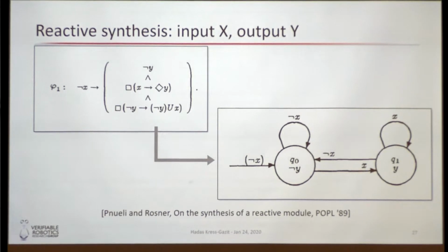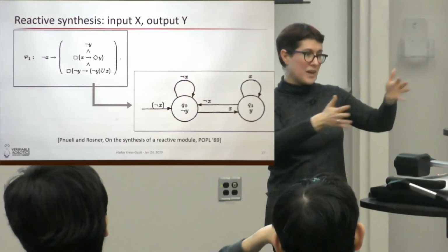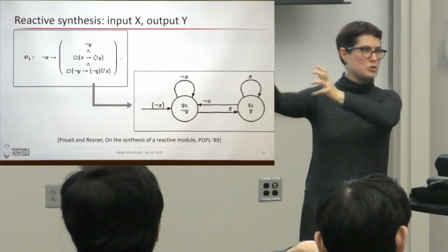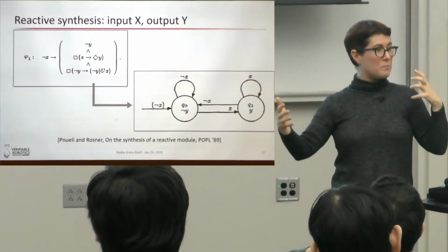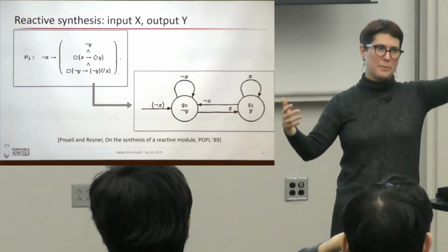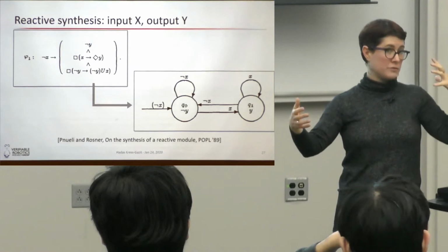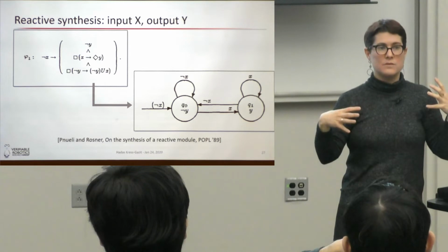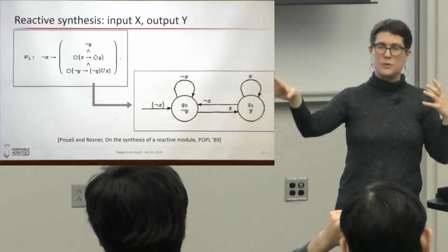The idea there is you have propositions that are inputs and propositions that are outputs. In robotics speak, we have sensors, or perception information, and we have actions, or actuation, or control. The information I'm getting, I'm not controlling. That's the environment, they're doing their thing. I'm getting information from that. What I'm controlling is what my actions are, the robot's actions. So X is input, Y is output.